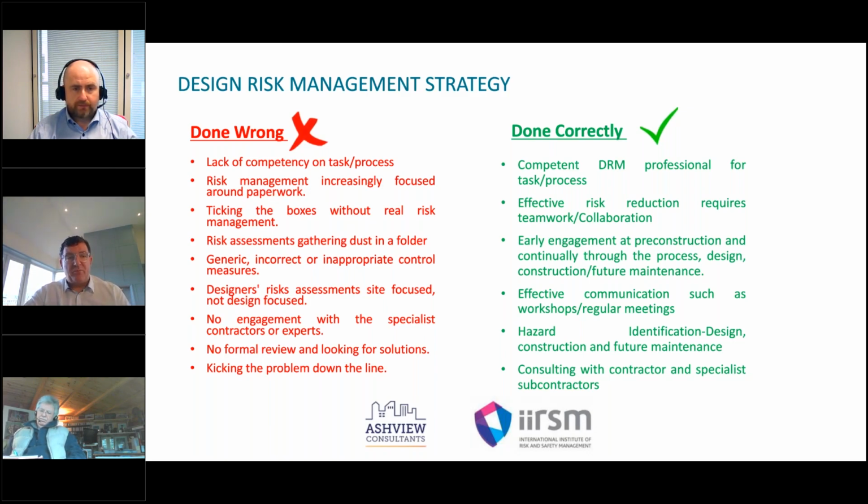Generic and incorrect or inappropriate control measures, design risk assessments that are site focused and not design focused, so they haven't looked at the mitigating measures. Quite often as a CDM and pre-construction assessor, you see information that's not focused on the actual design, it's focused on a constructability issue that you may not be able to design out. A competent contractor might ordinarily know that risk, and your job is to focus more on that design risk strategy, ensuring that you can design out the actual risks that are applicable to the designer.